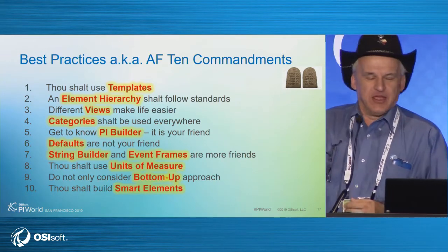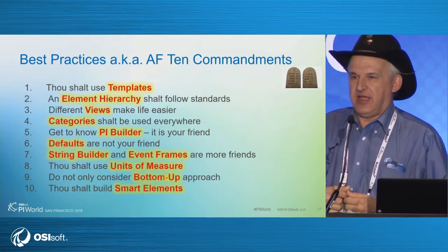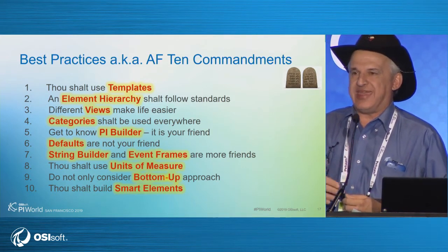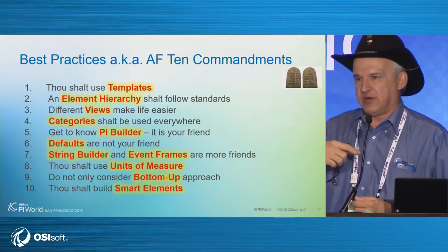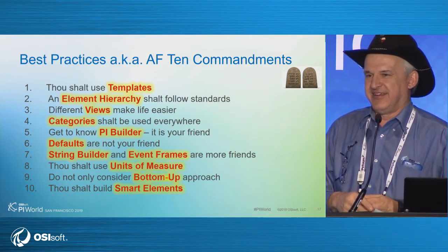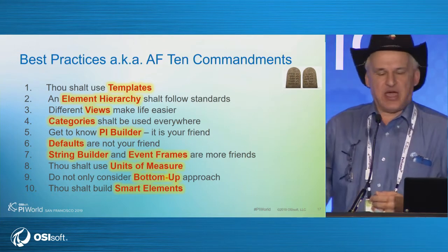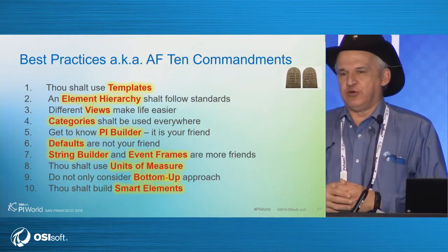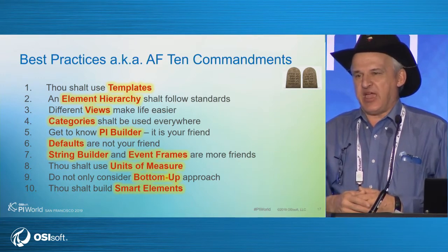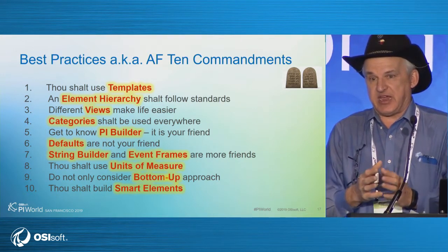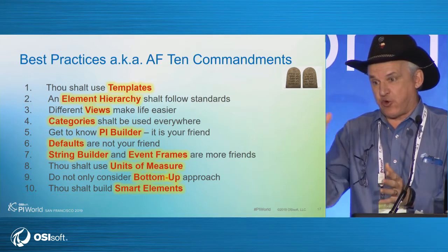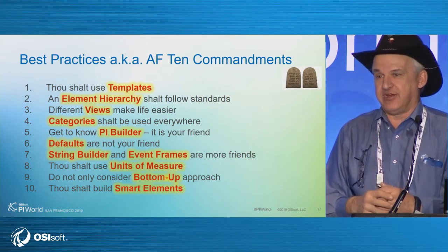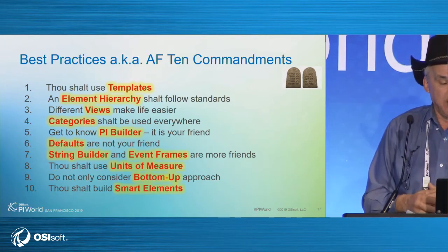So use templates. Pretty much all of our visualizations or things we do are keyed off templates. Even if I have one of them, I still create a template. Right? Okay. Element hierarchy, follow standards. We just talked about that. Different views will make your life easier. Right? So I have a main hierarchy, one or two hierarchies, but then I create views for specific things because I effectively group things in one place that will be scattered across your hierarchy. So views are good. Right?